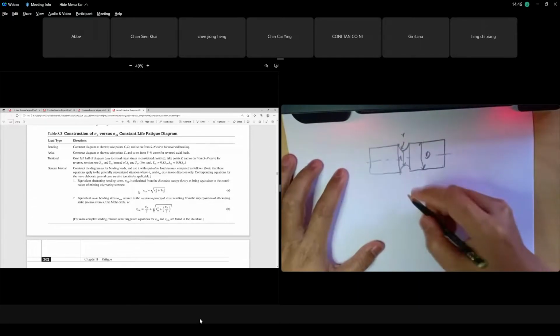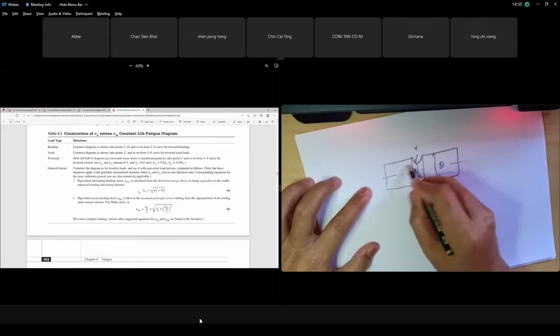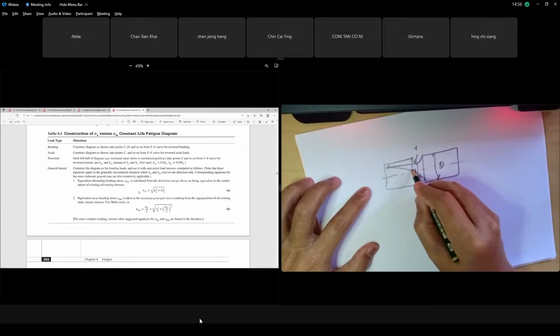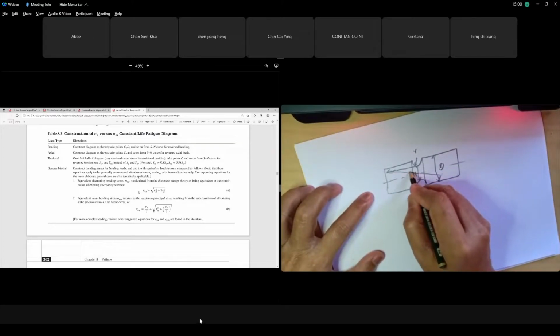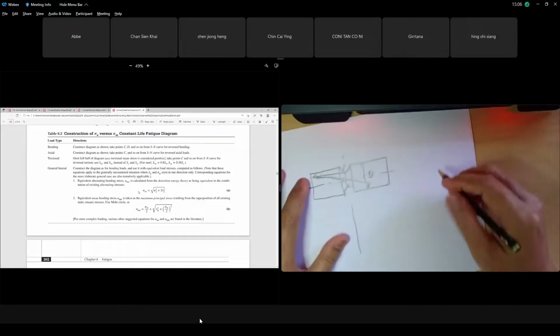Normally if it is a plain diameter, the stress distribution of this bending stress at that point is 0 at the neutral axis, right? But at that notch, it becomes so high, it stretches like this. If you just have a plain diameter, along the axis, nothing.